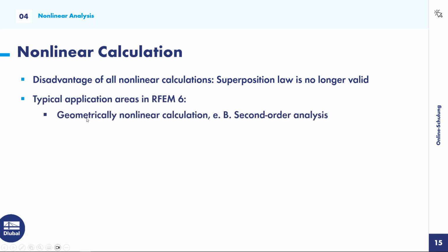Typical application areas of nonlinearities are nonlinear calculations like second order theory analysis, you might know it better as the P-delta analysis, which is the theory for small deformations. On the other hand, if you have large deformations like in membranes or cables, you would need the third order theory. We also might need to cover nonlinear material behavior.